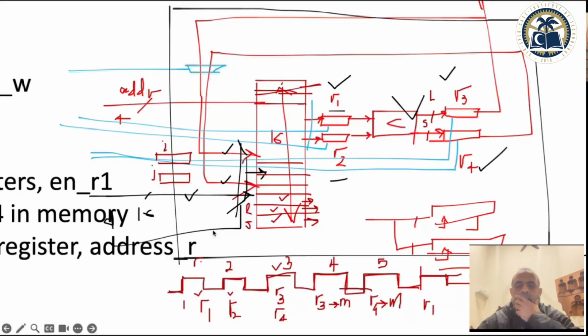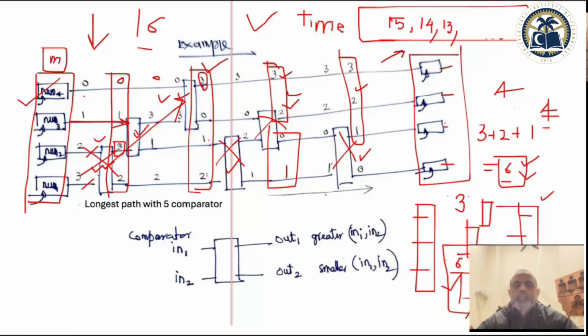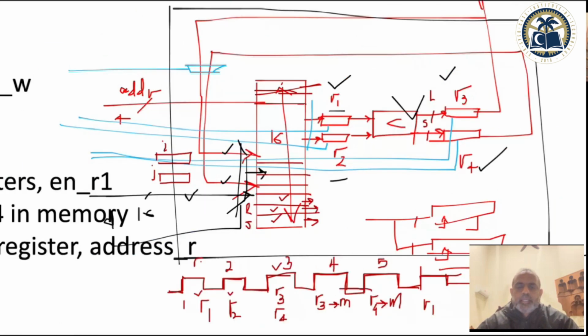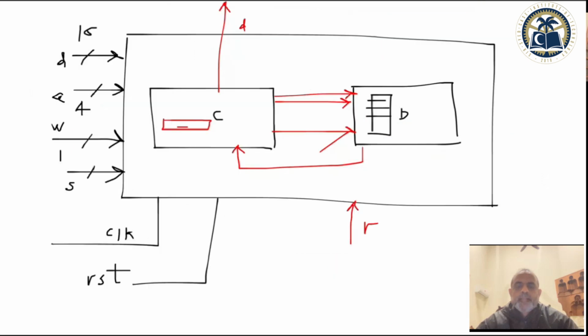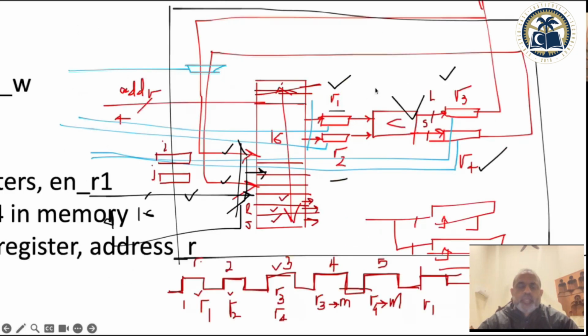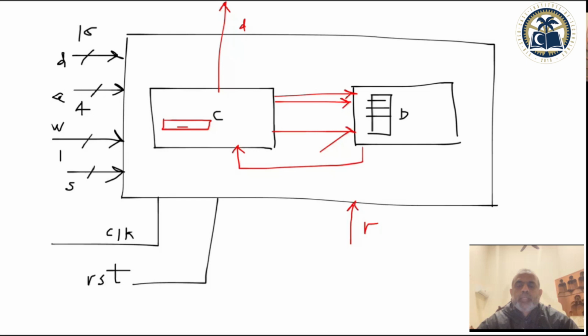So this is good. We know how to convert a fully dedicated architecture into a time shared architecture, and we have learned the data path and the overall design, where this controller is going to control and send most of the input signals which we have defined here. It will say write in R1, write in R2, write in R3 and R4, write in the memory, give the address.